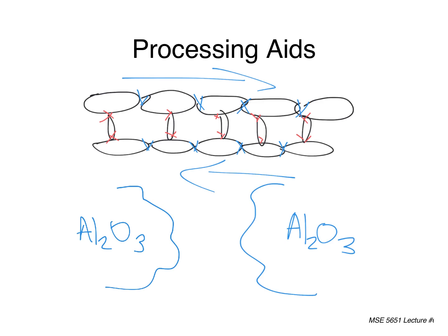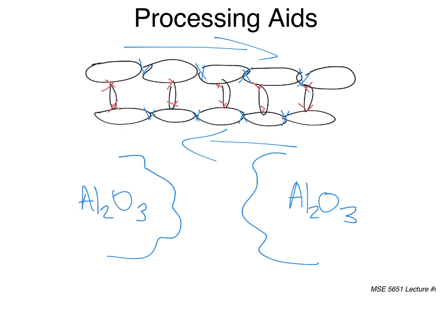So we know from what we talked about before that alumina is going to have a layer of water on it, because that's what these things do to minimize their surface energy. The first thing they do is form a layer of water, and it can be a monolayer at the very least, but more likely it's a multilayer of water sitting on those surfaces. And so we have this issue that those surfaces have an attraction to each other. They're both hydrophilic, and if you recall, we have Brownian motion trying to slam these two together, and when they get really close together, they can bond very tightly.